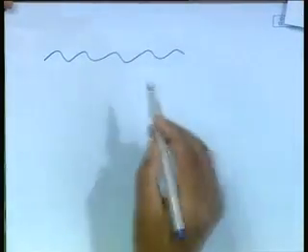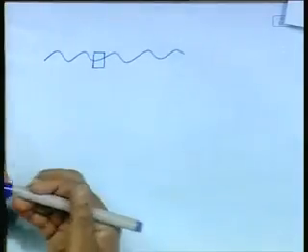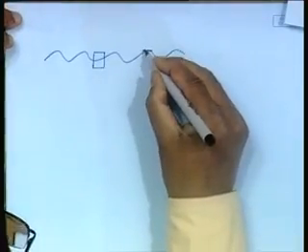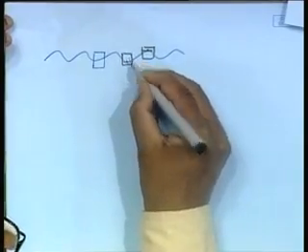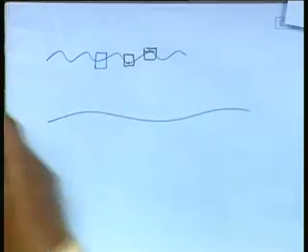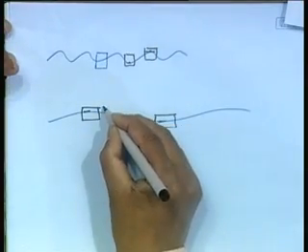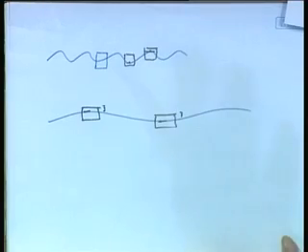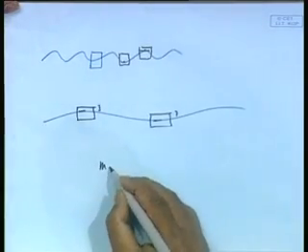So, we will find that you see three cases. One is high frequency wave, it is going like that, it is in this case sinking more, in here rising more, this gap is changing. Go to this long wave, it is always riding the wave, always having the same. That means this freeboard part remains more or less constant. And it is very easy to study this motion, because I do not have to actually determine Az, Bz, etc.